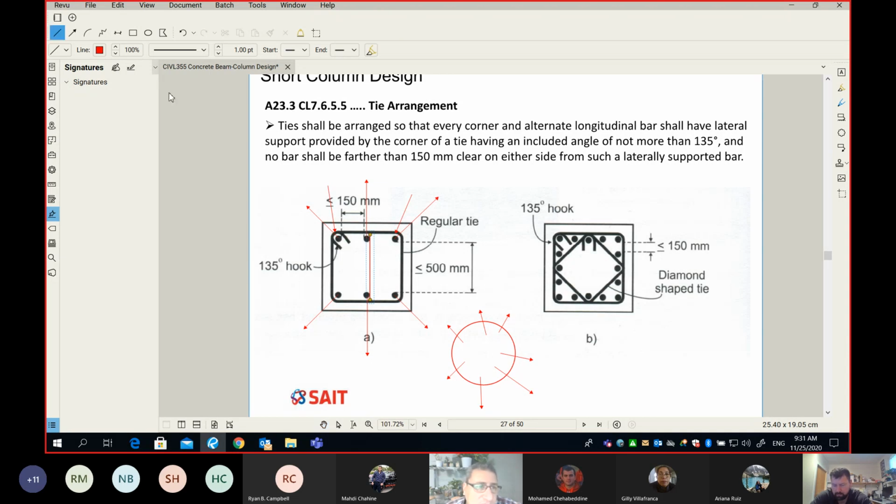this in place. Okay, I don't have the right tool, but think about it this way. I'm going to add a tie that wraps around those bars and simply holds them in place, preventing them from going outside. Are you guys able to visualize this? Yeah, yeah. Okay, now it makes sense. Once I add this extra tie, it simply stops those two bars from going to the outside or buckling to the outside, because this tie is weak.